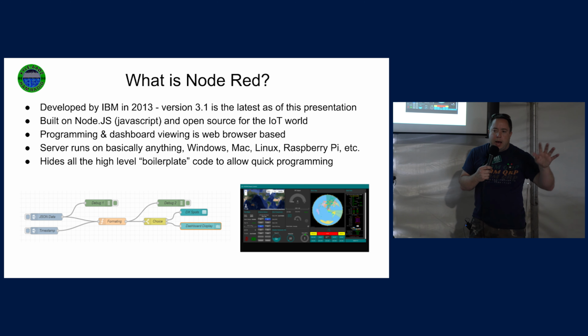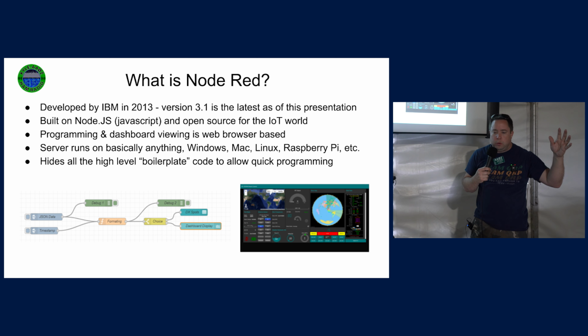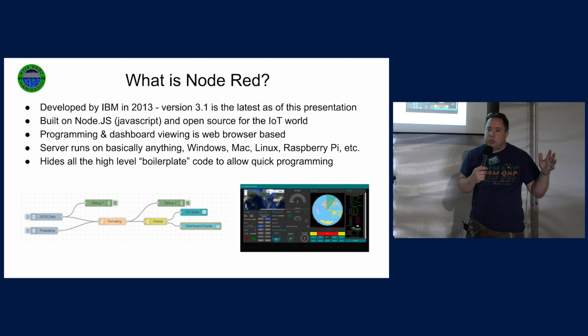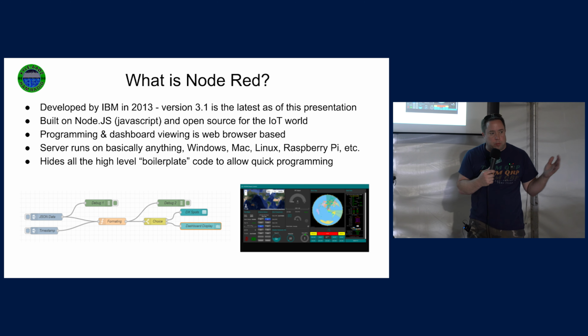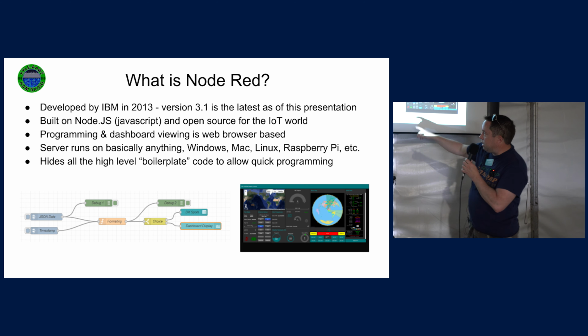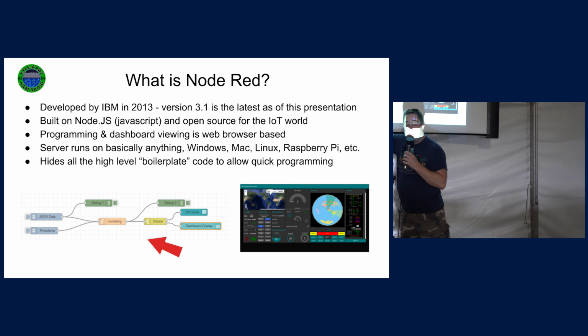So back in the day, I'm assuming, don't quote me on this, if you wanted to connect something to a TCP port, you had to do all of this back-end programming. Node-RED hides all of that stuff, and it's one node. You configure that one node with like 2 parameters, and you've got a TCP connection to whatever device you want. It's really easy.